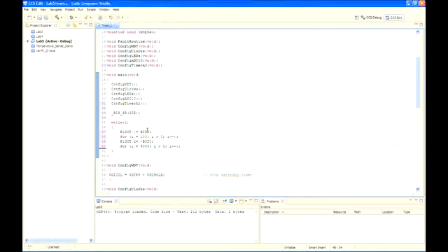This routine doesn't use any intrinsics, so when we're debugging the interrupts, they'll look good in C rather than dropping you back and forth between assembly. Oh, and don't forget to declare i at the top of main.c, volatile unsigned int i.